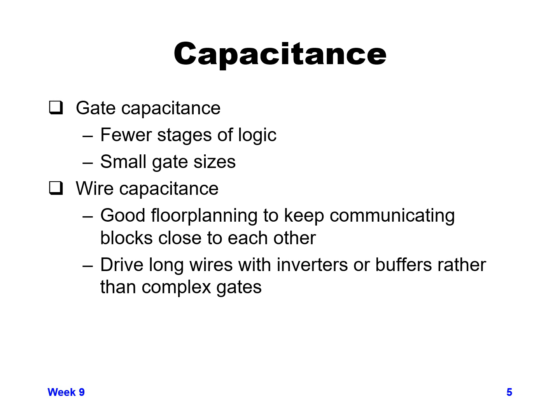could help your power. And then of course, if you can size your gates smaller, that can reduce your capacitance. And then wire capacitance is something that is fairly dominant nowadays. Your wire capacitance can be as much as your gate capacitance, depending on the logical function you're doing.